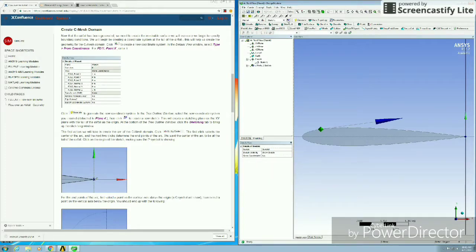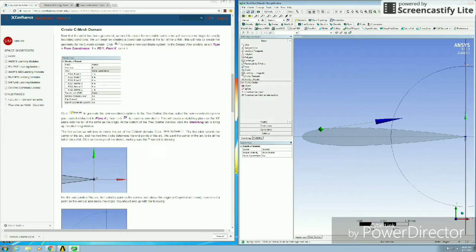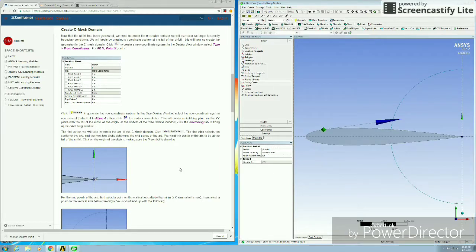So you're going to go hit the little sketching tab down here at the bottom, and you're going to find arc by center, and we're going to go click in the center. It's going to bring up a P. You want to make sure that P shows. We're just going to go to the center. You see the little P, and then you're going to go up top, and then you're going to rotate counterclockwise and click on the vertical axis twice.